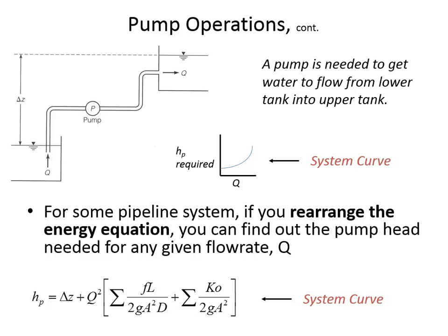At the end, the EGL was above the water surface, and the HGL stopped at the water surface. And so this V squared divided by 2g, the magnitude of the energy grade line above the hydraulic grade line, that's an energy loss. And so the K value you should use for an exit is 1. And for an entrance like that, the K value is 1.